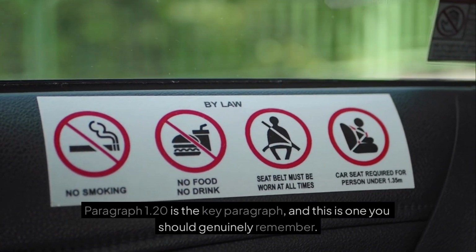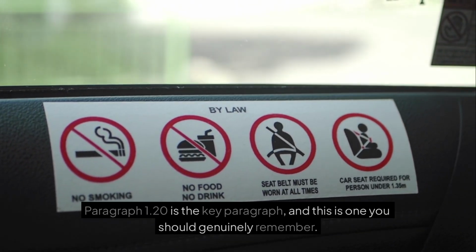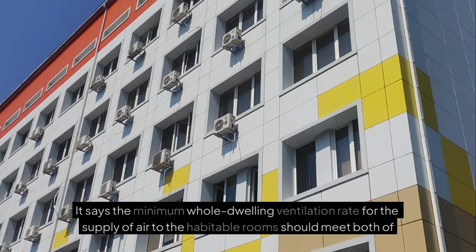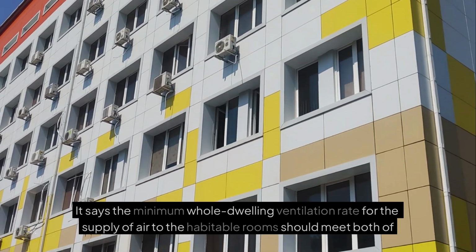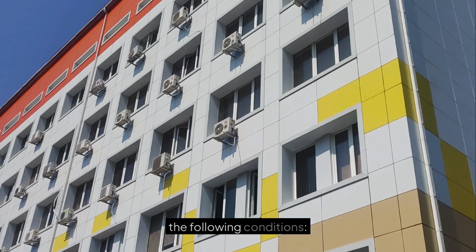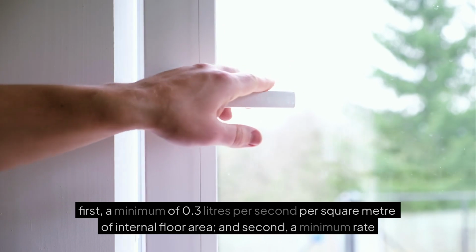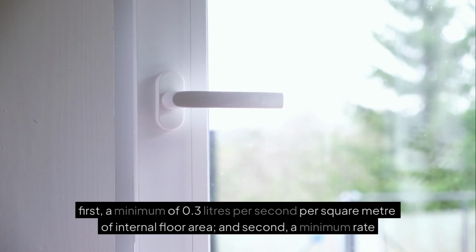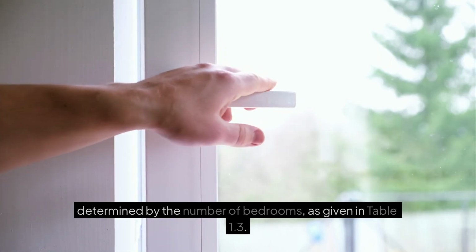Paragraph 1.20 is the key paragraph, and this is one you should genuinely remember. It says the minimum whole dwelling ventilation rate for the supply of air to the habitable rooms should meet both of the following conditions. First, a minimum of 0.3 liters per second per square meter of internal floor area. And second, a minimum rate determined by the number of bedrooms, as given in Table 1.3.